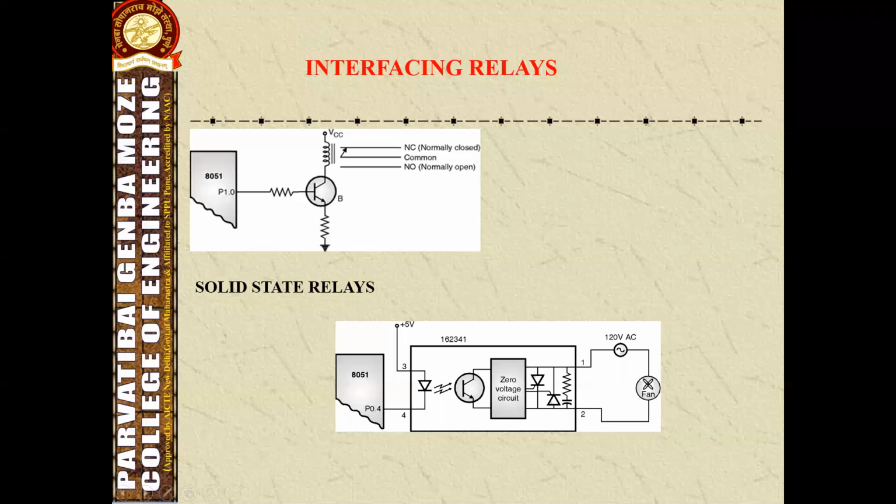Now let's see about the solid state relay. A solid state relay is a solid state electronic component that provides a similar function to an electromechanical relay but does not have any moving component, which increases the long-term reliability. With the early solid state relays, the trend came from the fact that a transistor has a small voltage drop across it, and this voltage drop limited the amount of current a given solid state relay could handle. As transistors improved, the higher current the relay is able to handle, 100 to 1200 amperes have become commercially available.